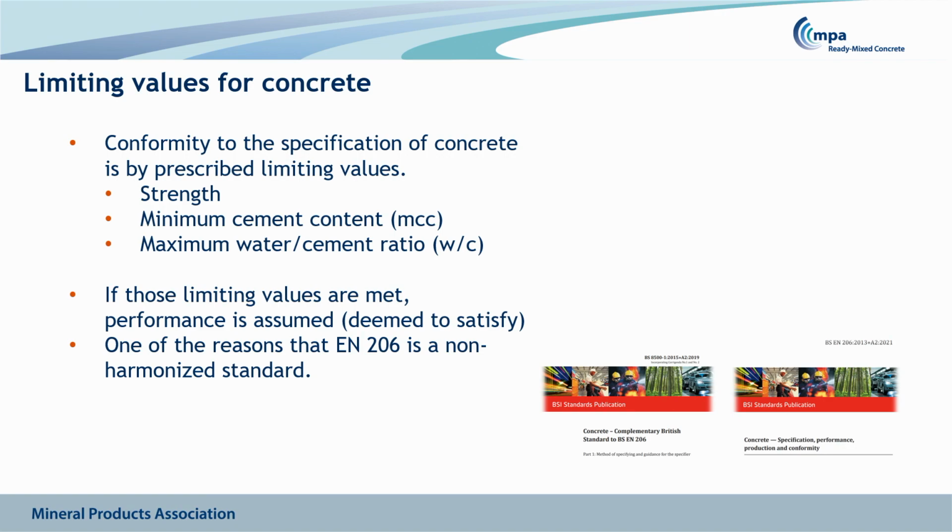But this is one of the reasons why EN 206, the European standard, is non-harmonised: deciding limiting values of strength, minimum cement content, and water cement ratio for all materials across Europe in all exposure conditions, whether it's in Norway or the south of France, is almost impossible. And so we have the UK values for these. And you could actually say that these are possibly conservative, because concrete in the north of Scotland does not necessarily have the same requirements as concrete in the south of England, but we use a UK-wide figure.